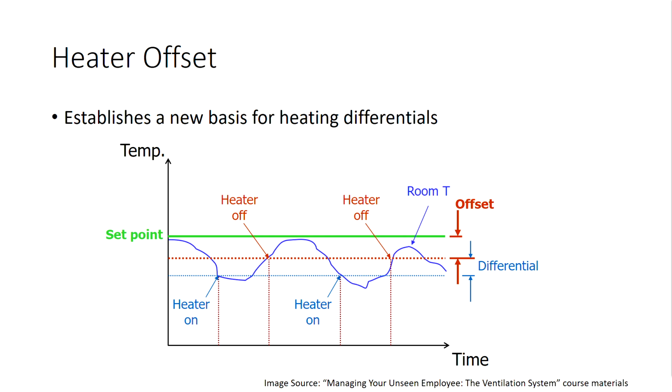You notice some overshoot in this example figure. Heating often continues after the heater has turned off. The amount of overshoot depends on many things, including the size of our heaters, but is something we need to keep in mind, and we're going to show some implications shortly.